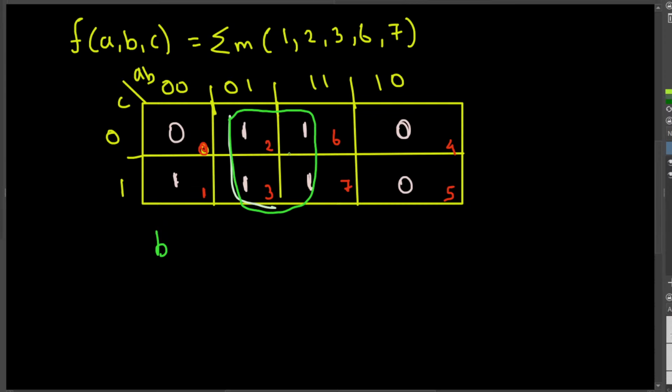Next thing we have to look at is, can we group this by 2? If you look at this, I can group here by 2. You only group if something was not grouped. I cannot group these two because these are already grouped. But since I have a 1 outside here, I have to see, can I group this one with 4 of them? 4 is not possible, so I can group with 2 of them. So for only that one, I take 1 from here.